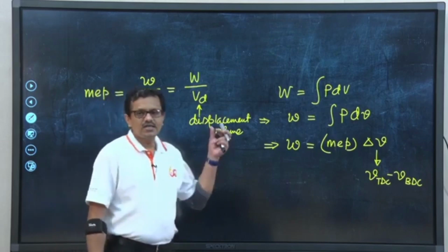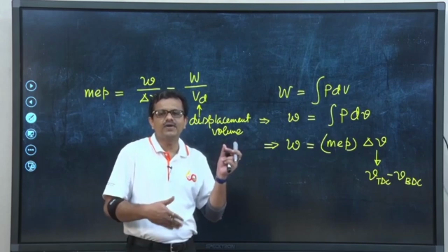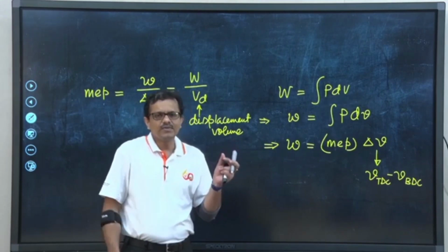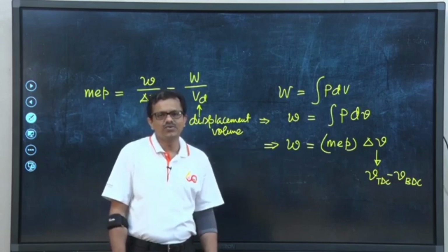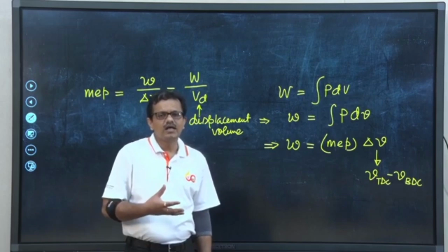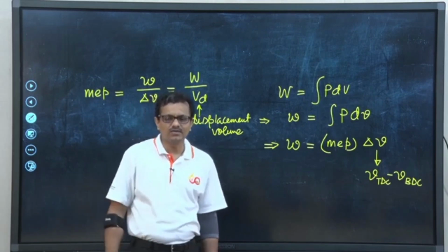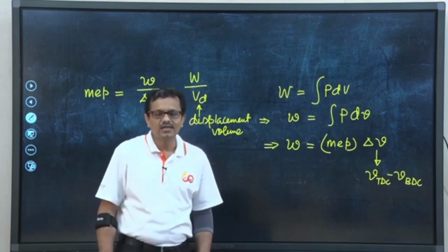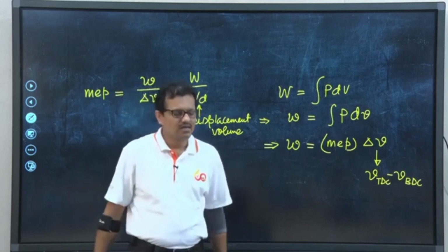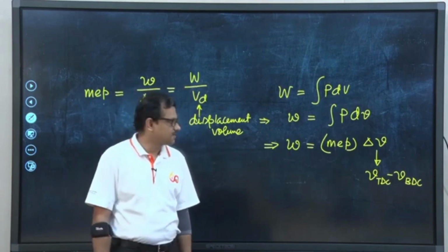So, if we consider torque as a common parameter for comparing engines in terms of the design as well as output, maybe larger engine always will look better, while if we consider power as the parameter for the comparison of engine performance or engine design, then definitely higher speed becomes important.